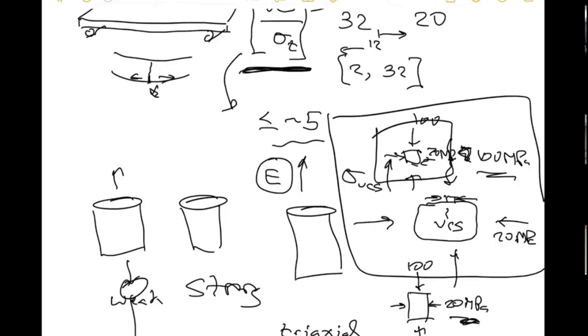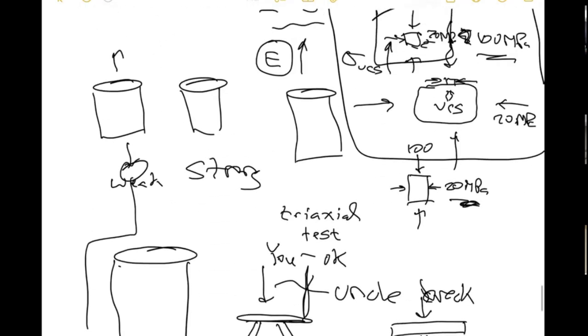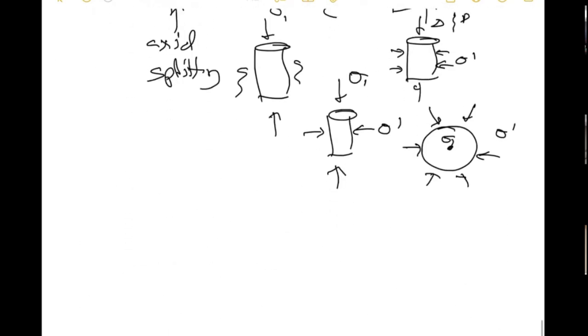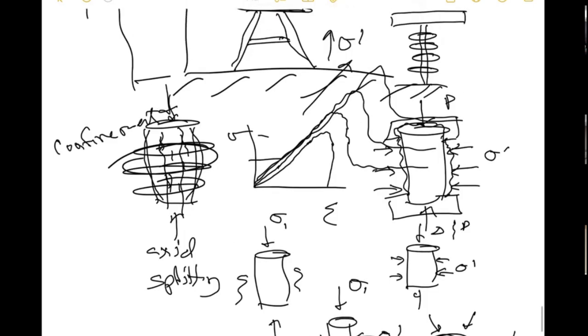But now we make an excavation, everything changes, the boundary conditions change, and there's no stress on this face. And it's kind of like a UCS test. And so it's weaker. That's why rock gets damaged when you make excavations. You're changing the loading. And so the take-home point of this, and the last thing, if you take these values of sigma prime, they're increasing.